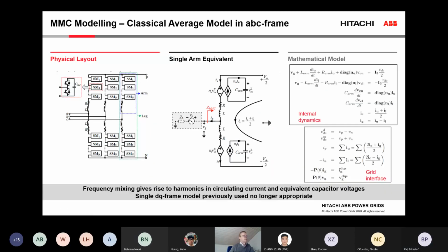That means you need to use some knowledge about your system when moving from the generalized DQ equation set back into the single DQ frame we use for the grid. I think this is connected to your question. Yeah, thank you. You may need to derive the detailed answer based on my explanation yourself. You have to make assumptions there. Yes. And one assumption is that the third harmonic doesn't pass through.